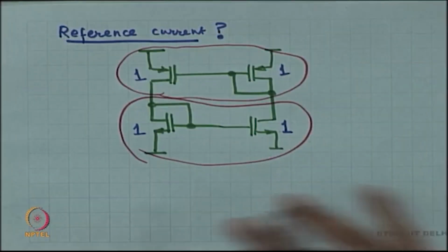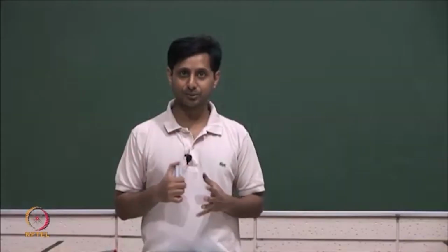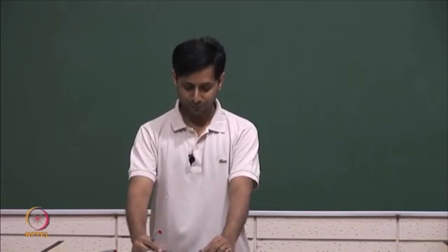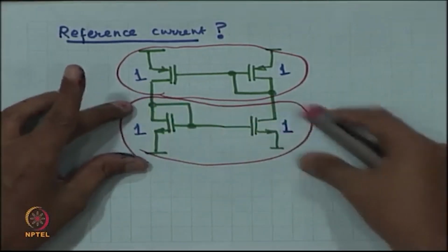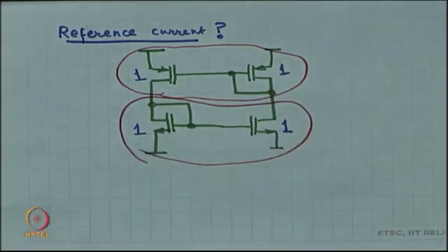You can't start treating every device on its own and looking at its characteristics and so on. You are no longer in class 10, class 11, class 12, right, you are studying engineering, you have to move ahead. So, when you start moving ahead, you start recognizing patterns. So, this is a pattern, this circuit is a block, this is a current mirror, right. You have to identify the current mirror and then use it accordingly in your analysis.